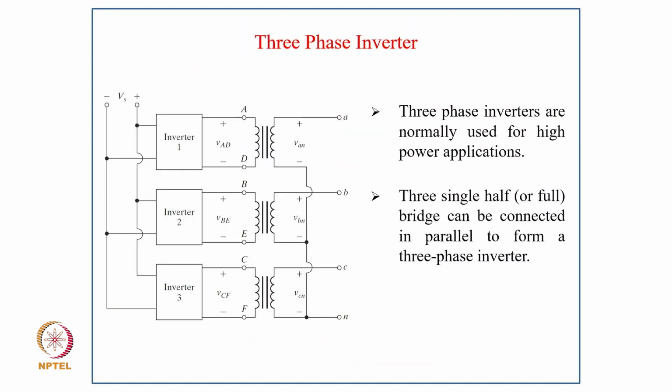And three-phase inverters are normally used in high power applications. And three single-phase half or full bridges can be connected in parallel to form a three-phase inverter.